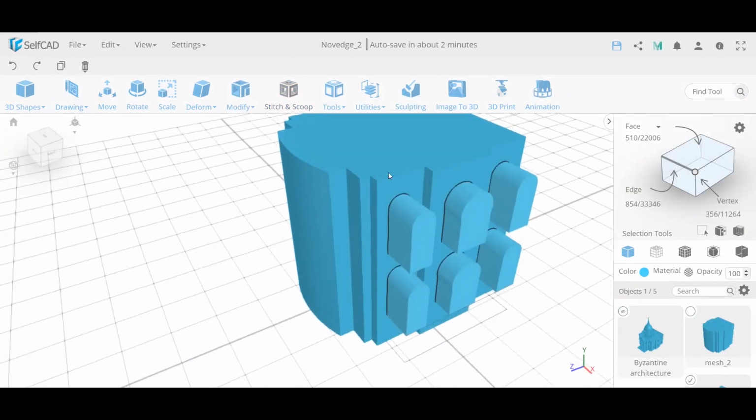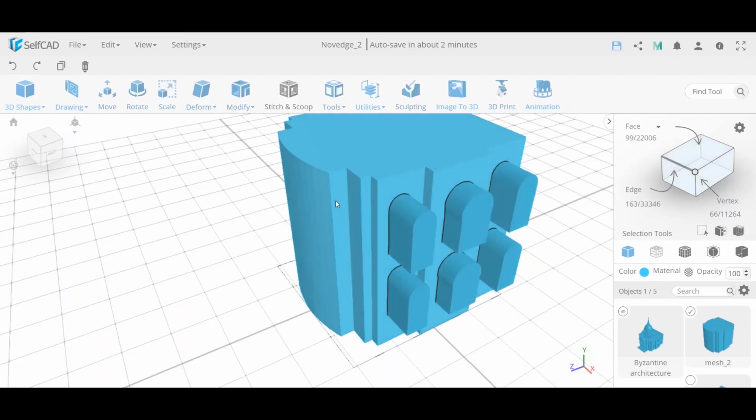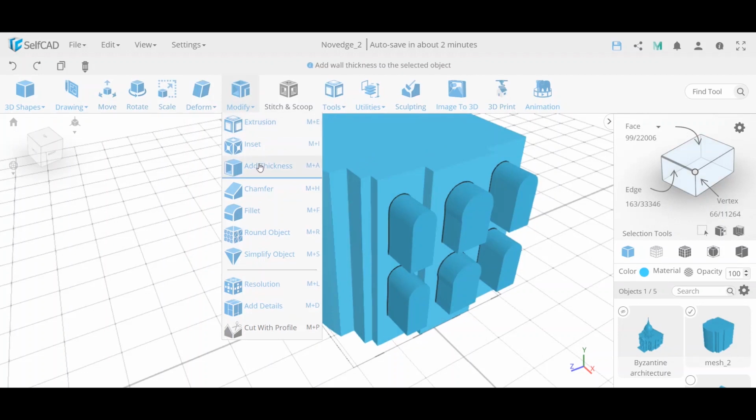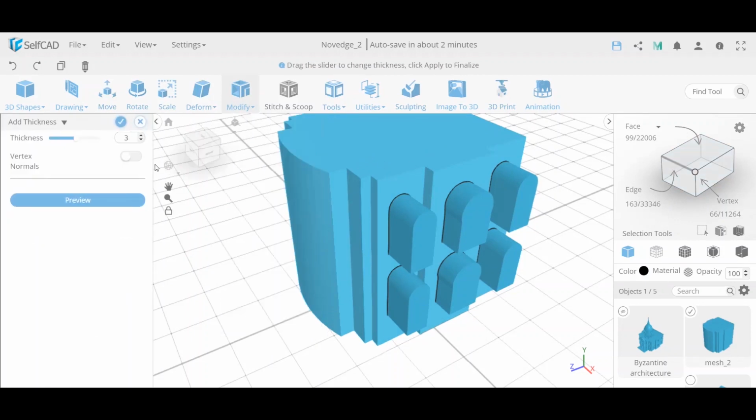If you're going to model, you probably model the walls separately and the floor and roof separately, and you add thickness. But if you have something like this, it's not suggested to add thickness to enclosed objects. You don't see what's happening and you make it non-manifold, so you probably will have to open it and then add thickness. But nevertheless, this should do the trick for now. So I'll add thickness of -5, let's say, to add something.